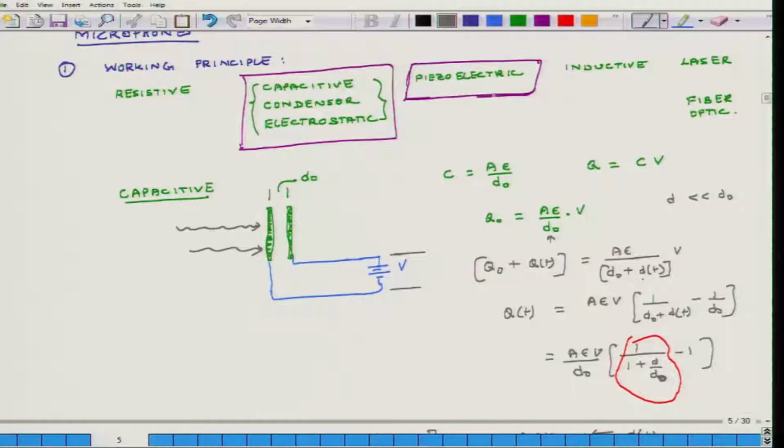In piezoelectrics, what happens is that you have a piezoelectric crystal and you apply some initial voltage across the piezoelectric crystal, so it is a little bit compressed because of that, and then when some pressure hits the piezoelectric crystal, the working principle is that when you press a piezoelectric crystal or expand it, there is some additional voltage generated. So that change in voltage is sensed, and with that change in voltage you interpret that in terms of pressure.